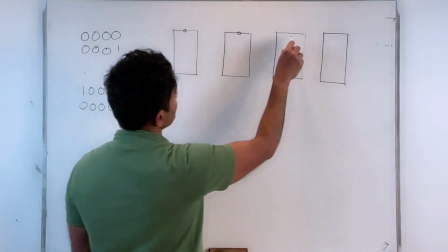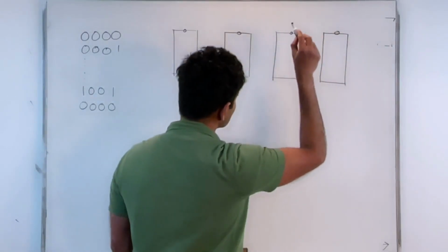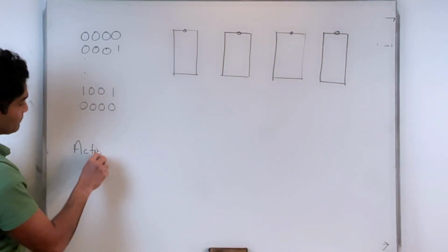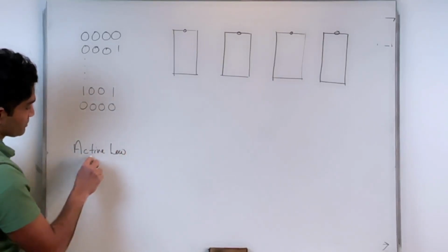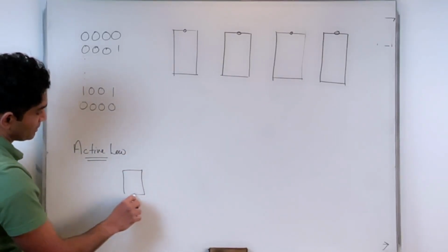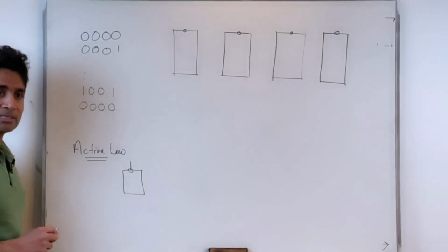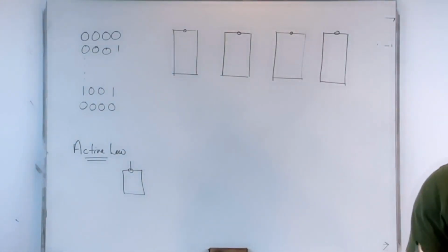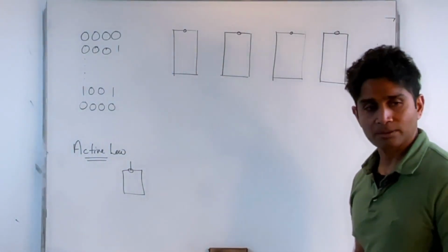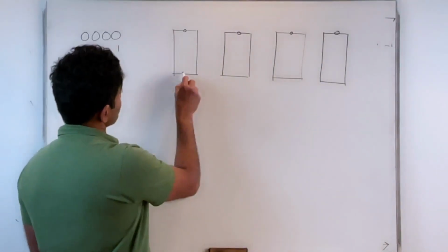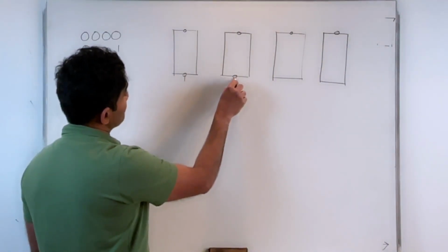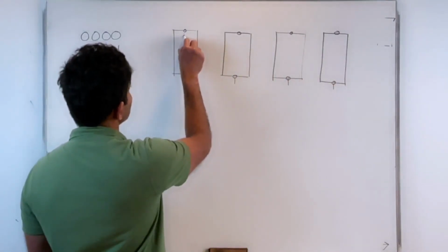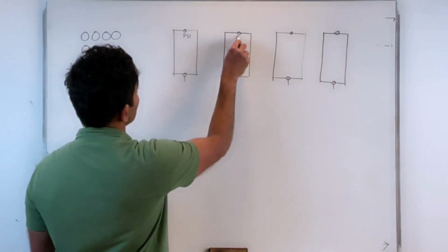And each of these inputs are active low. Again, when you're reading about anything and it says active low, you know what that means. That is represented by the bubble circle, and you need to apply a 0 input to make that input active. If you don't want this to be active, then these have to be always at 1, at a high value. So that's my preset for each of my flip-flops,